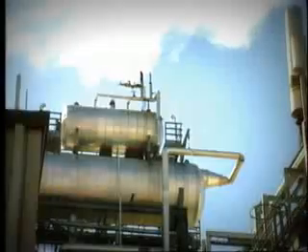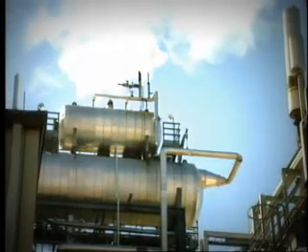The presence of dissolved oxygen in feed water is a prime cause of corrosion in boiler tubes. Removal of as much dissolved oxygen as possible is essential. And normally we try to limit the amount of dissolved oxygen in feed water to as low as 2 or 3 parts per billion. A typical de-aerator looks like this.